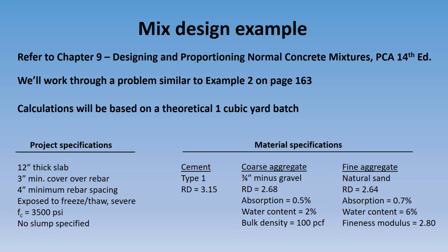I had you do a homework example last week on fineness modulus. That's just a variable that you can calculate from a set of gradation results based on the summation of percents retained on specific sieve sizes on a sand's gradation.